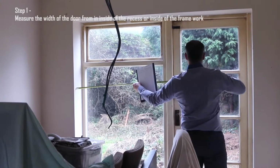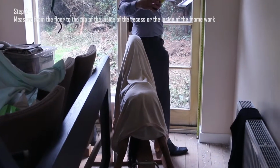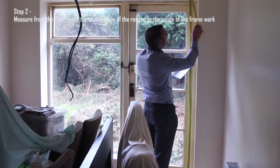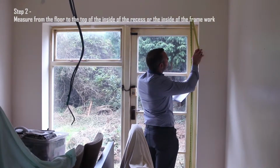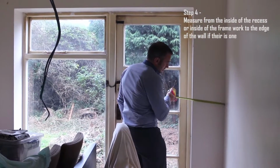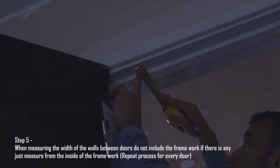When we're measuring doors or windows, we're going to go between the reveal. Then we want to measure the height as well. So we measure the door height internally, and then we're going to measure the reveal over the top of it. Measure the inside recess to the window. Give us an idea of wall thickness by measuring across the internal width of the door frame.